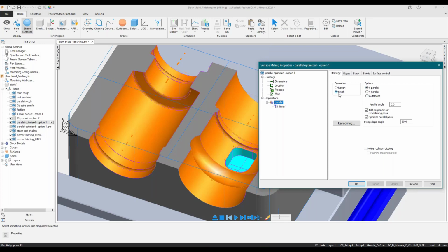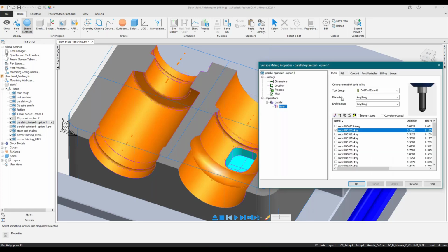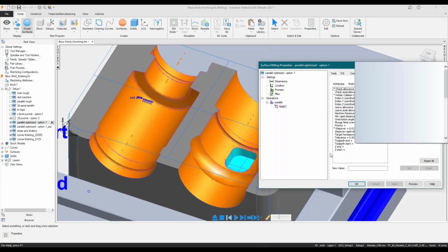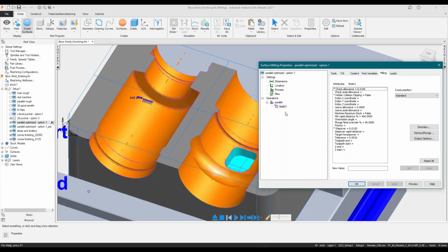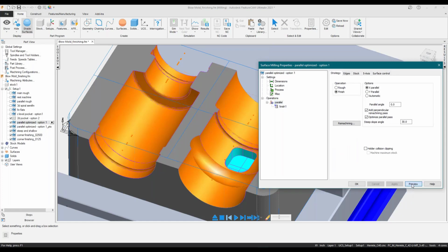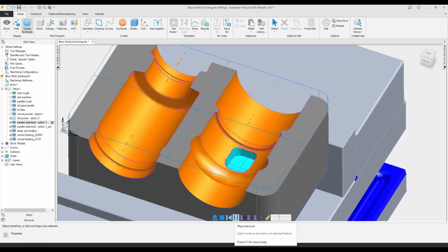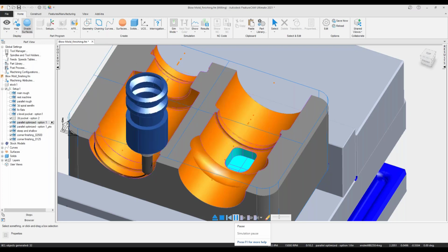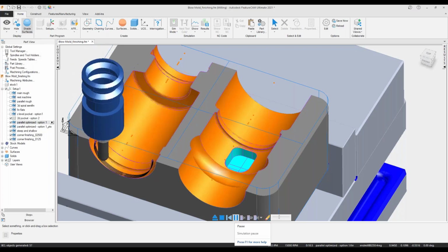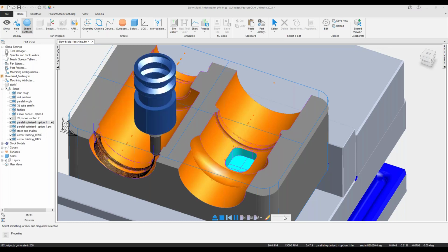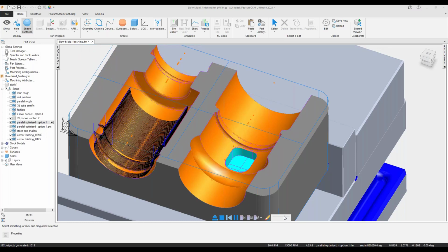We're finishing, so I'm going to machine this to 0 stock. I've already gone ahead and changed the type of options. If I were to jump into the finish 1, go into milling, I've already changed my step overs, perhaps tolerance. Let's jump back into parallel real quick. Let's do a quick preview and play. Okay, so you can see how the tool tracks back and forth in a linear type fashion. And I'm just going to play this simulation a little bit quicker here, and I'll explain what is happening.